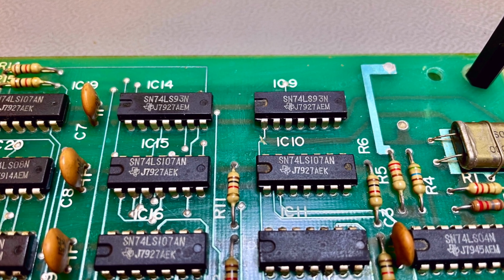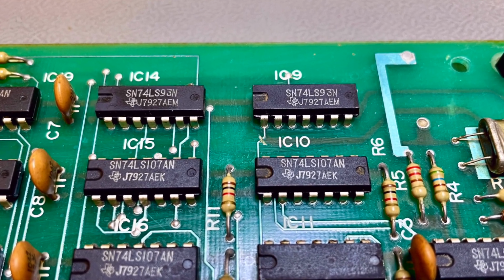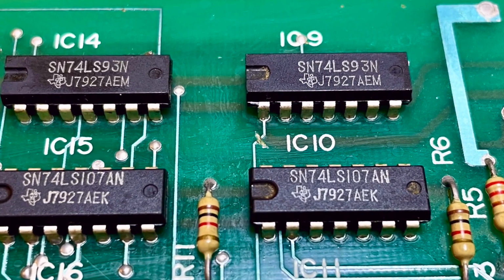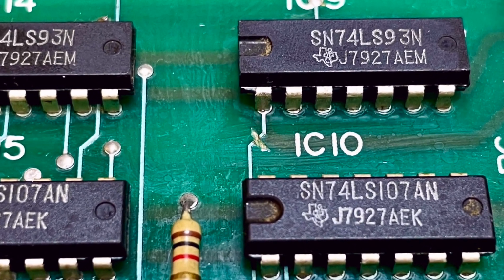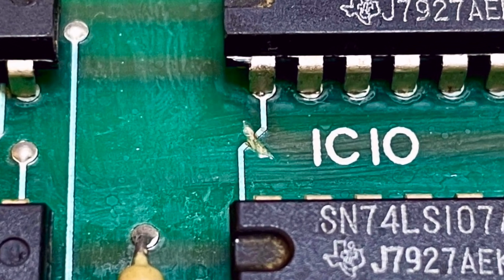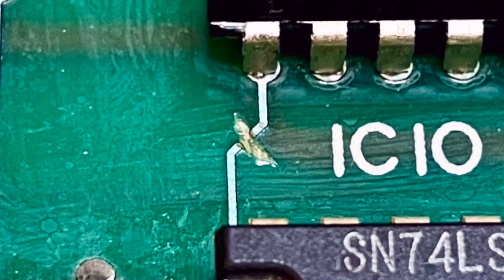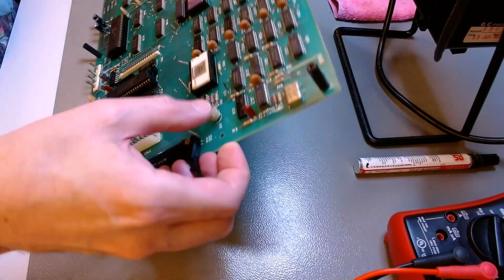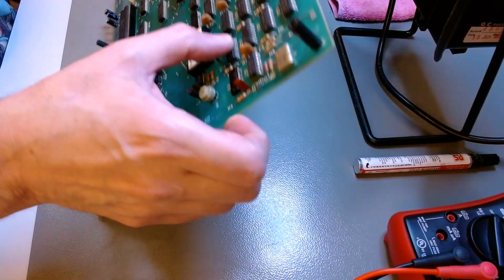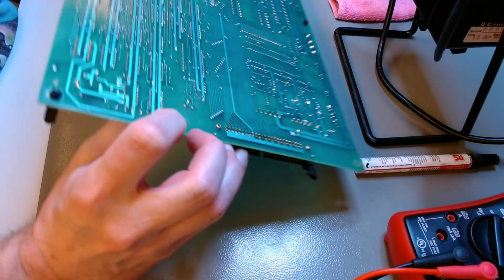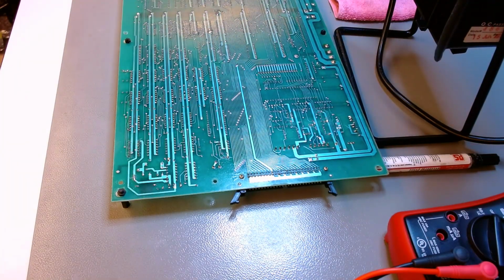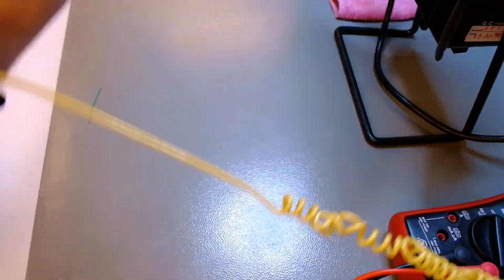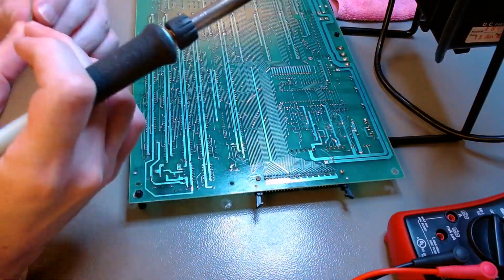And sure enough, there is the cut on the trace, exactly where I thought it would be, breaking both of the connections I talked about. There it is. It was cut by the previous owner as part of some modification. So I study the board and find a conveniently placed via already on the board. I will use that to place a bodge on the back side using very thin wire. You see me preparing that now.